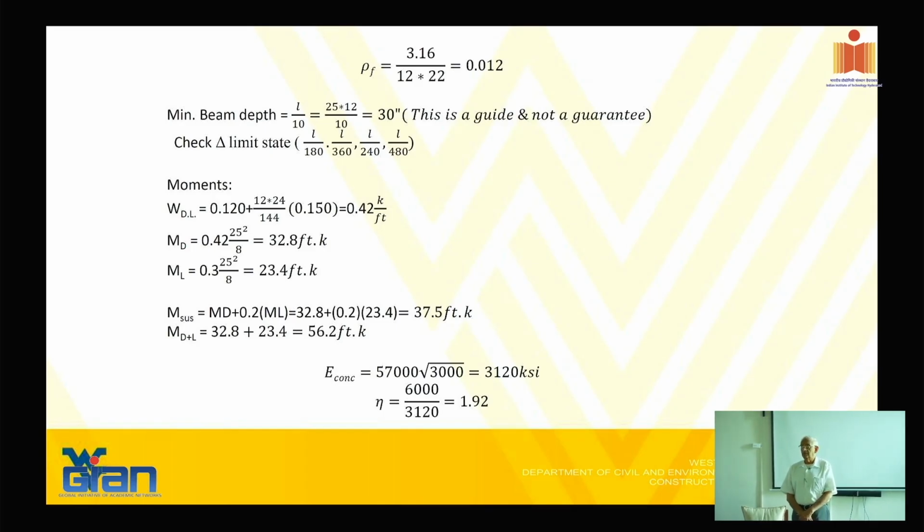For pre-stressed material elements too? It's 1/3. We use 1/3 as the, I mean, if the modulus of concrete is 4.5 million for static loads, for creep load we say it's only 1/3 of that, which is 1.5 million PSI.